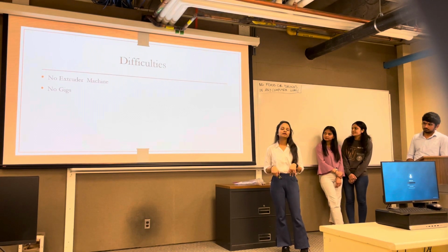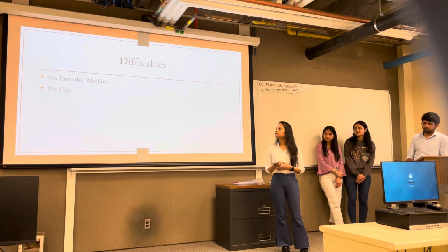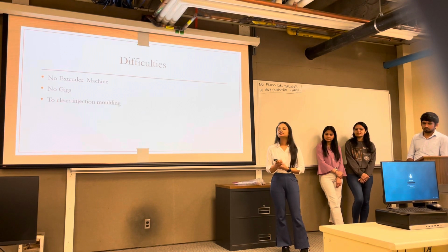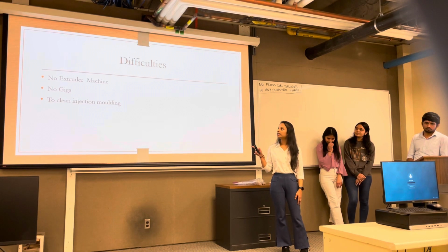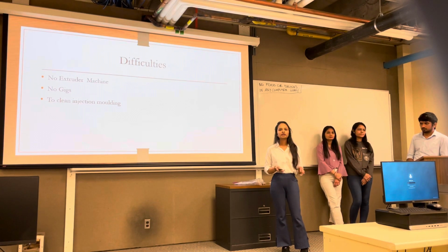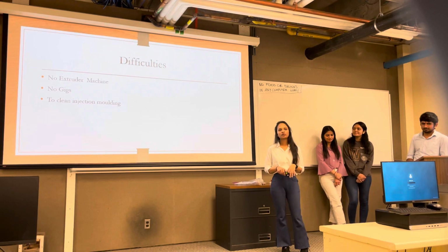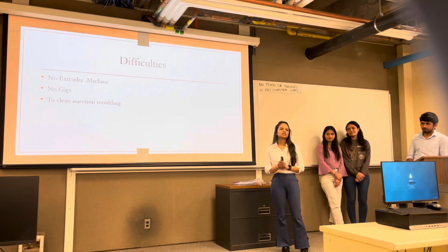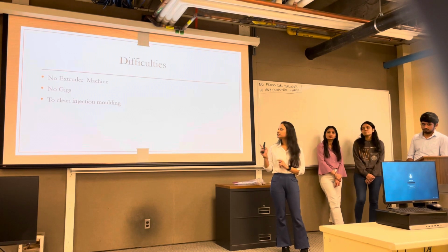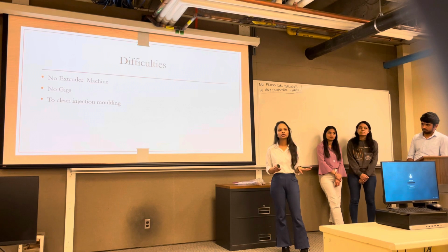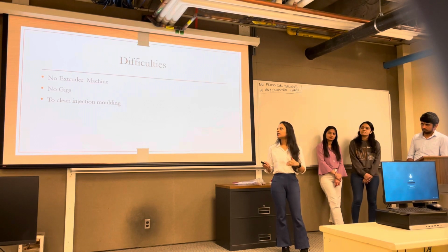We planned to test the impact, but we don't have jigs, so we didn't do that. We also faced a challenge in cleaning the injection molding machine. From the start of the term to the end of the project, we spent almost 7 to 9 hours of lab time just cleaning the injection molding machine. The professor also suggested during the meeting that it's good to use a cleaning agent. So we used a cleaning agent, and that helped us a lot to clean it faster.